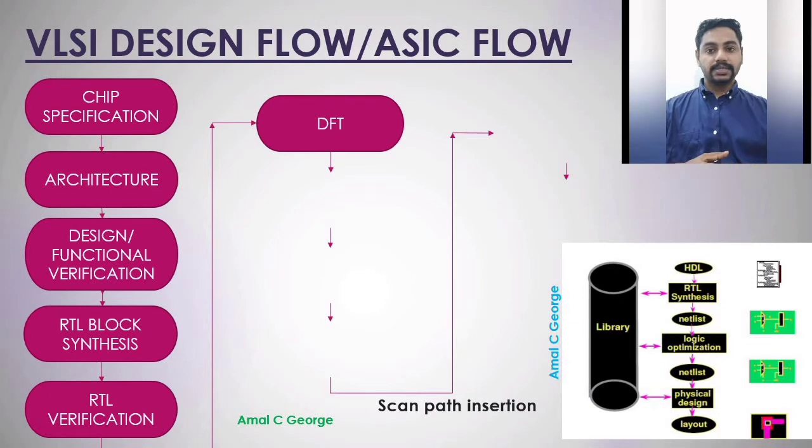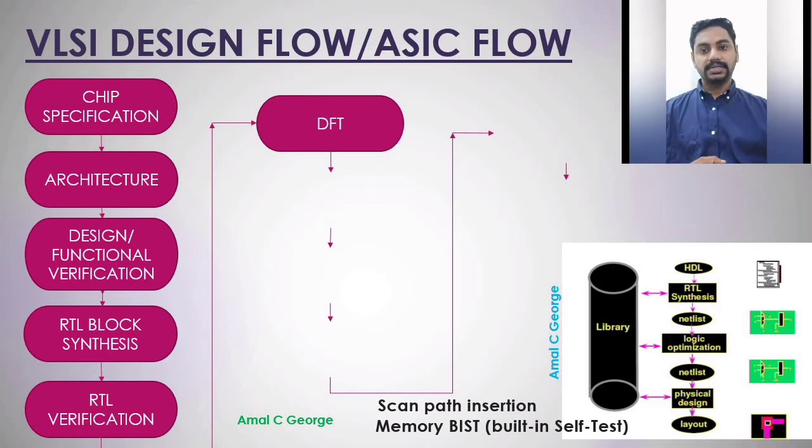The second step is memory BIST, meaning MBIST, built-in self-test. In the lower technology node, chip memory requires lower area and fast access time. MBIST is a device which is used to check RAMs, random access memories. It is a comprehensive solution to memory testing, errors and self-repair proficiencies.